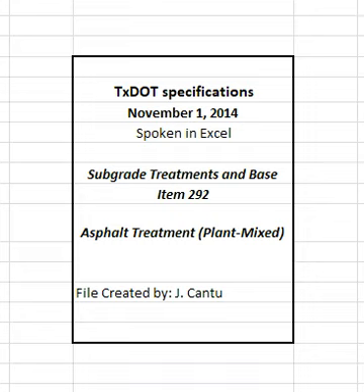4.4.1 Weather conditions. Tack coat and mixture may be placed only when the roadway surface temperature is 60 degrees Fahrenheit or higher unless otherwise approved. Measure the roadway surface temperature with a handheld infrared thermometer. Place tack coat or mixtures only when the engineer determines that general weather conditions and moisture conditions of the roadway surface are suitable. The engineer may waive placement temperature requirements.